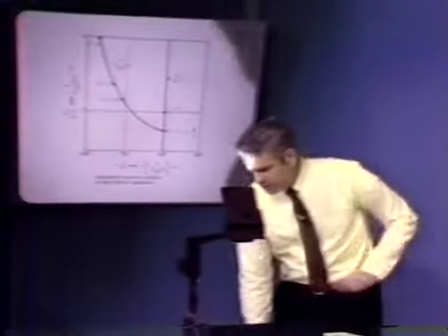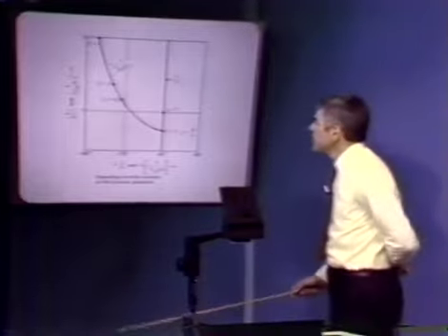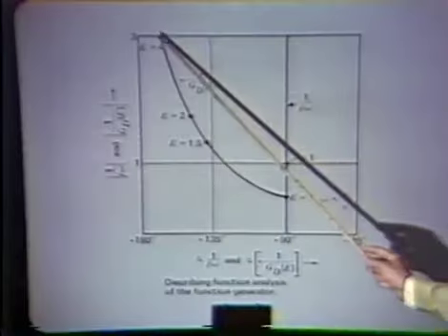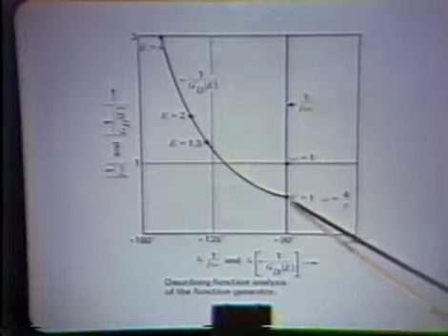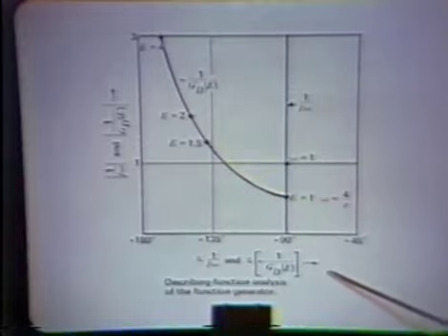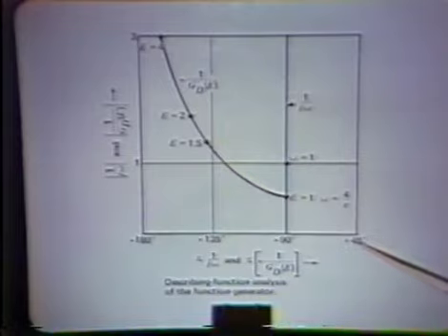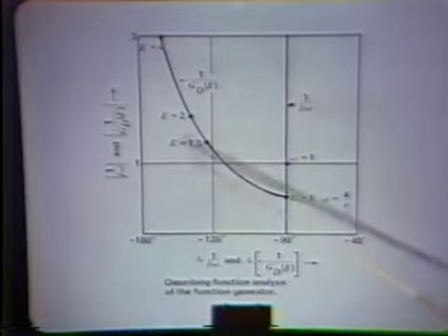We can use that information as part of our describing function construction. Here we have minus 1 over g sub d of E. We're showing this, of course, as we always do in a gain phase plane, the angle running from minus 45 degrees, in this case, to minus 180 degrees.